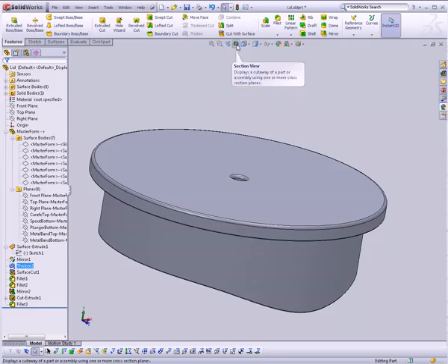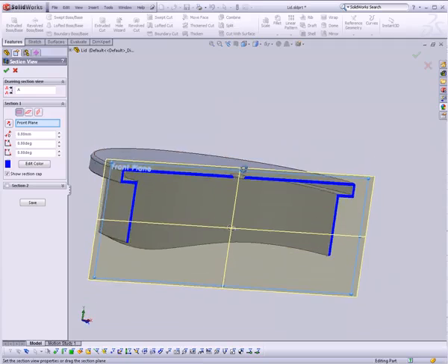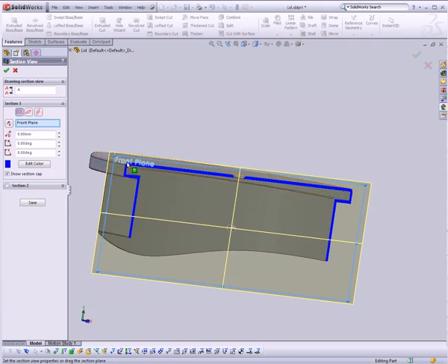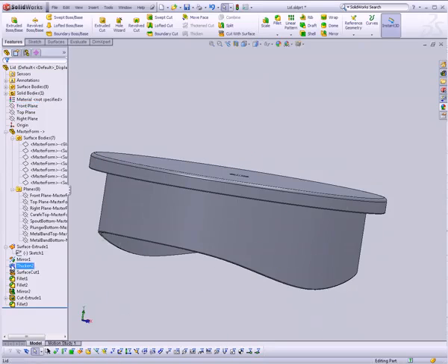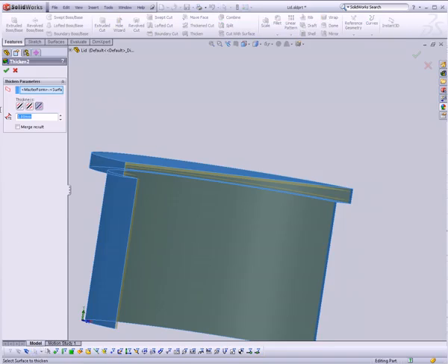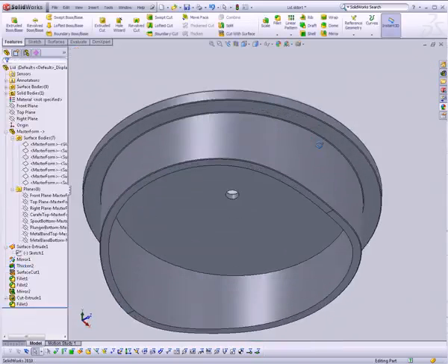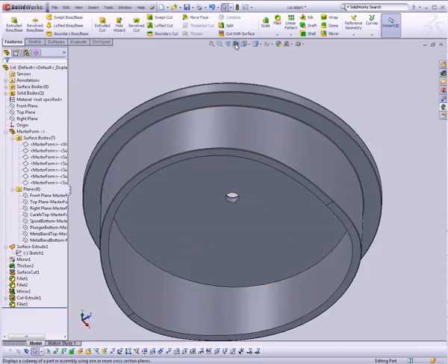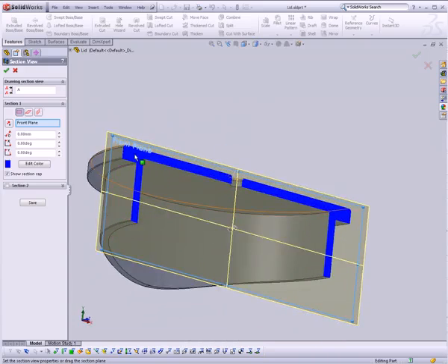And as you can see in our cross-section, we get this going on up here, which is not realistic. We need this to be filled in. So rather than actually changing the wall thickness, let's change that back to 3. We'll leave that just the way that it was originally, so that our cross-section is solid up here, which is what we want.